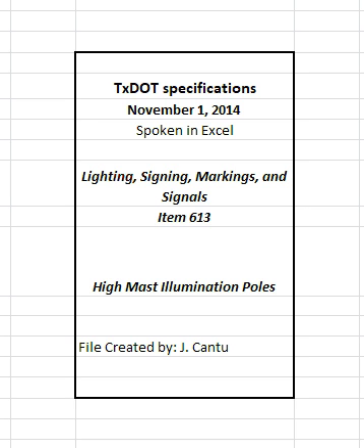3.4.1 Foundations. Construct foundations for high-mast illumination poles in accordance with Item 416, drilled shaft foundations, and the details shown on the plans. Before placing concrete for the drilled shaft foundation, inspect anchor bolts to verify proper projecting length of bolts, bolt pattern, orientation of pattern, bolt alignment, and bolt galvanizing are as shown on the plans.